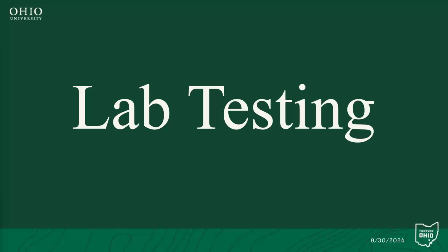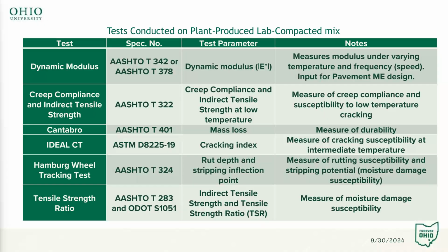Now we go into lab testing, trying to characterize the material from the field in the lab, so we are able to provide ODOT with values they can use in their future design. The set of tests that was conducted included dynamic modulus according to AASHTO T342 and T378, creep compliance and indirect